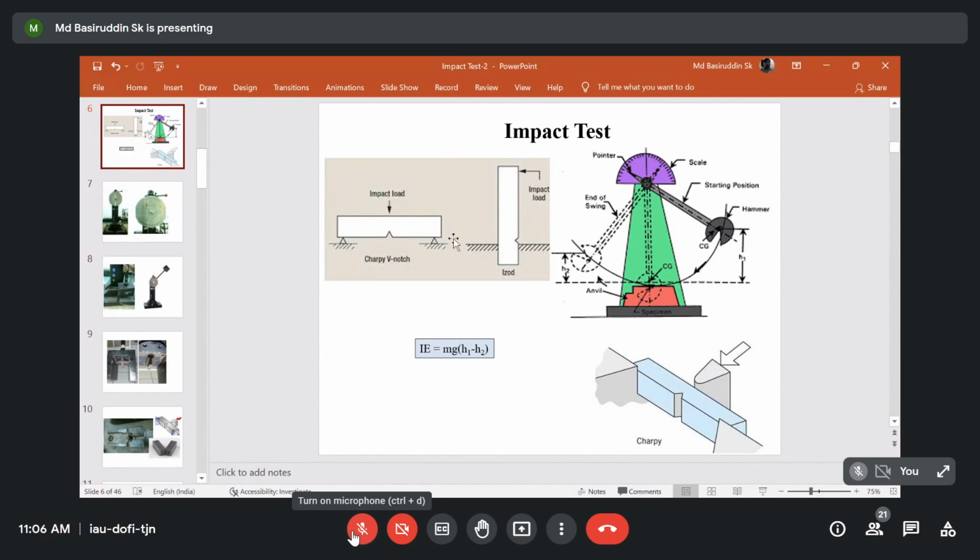That 3 point loading condition is there in the case of Charpy impact testing. But in Izod impact testing, you find a 2 point loading condition, where one end is fixed over the anvil and the other end is free, and you apply the load at the free end. Your material should be put in this position such that the crack will initiate and propagate quite easily from one end to the other.